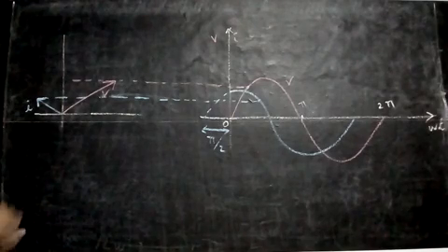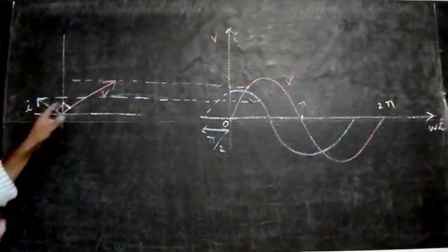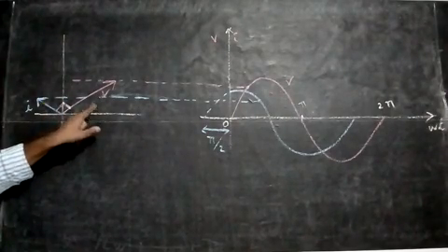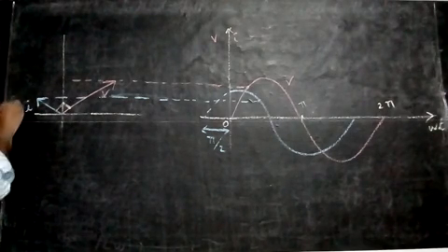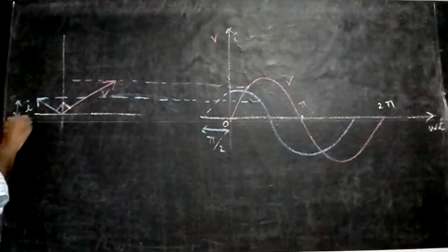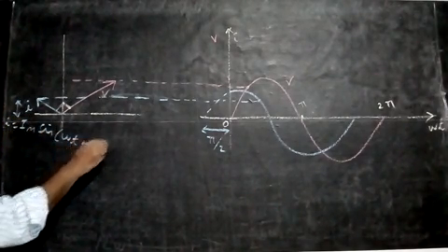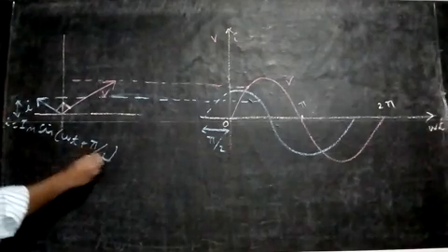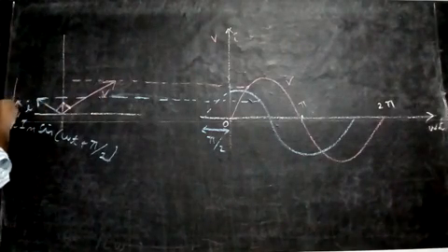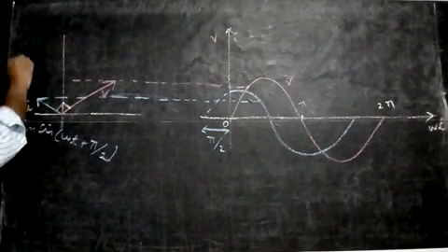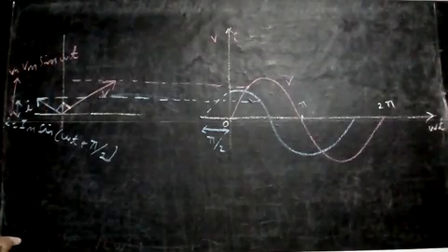So see that now the difference between current and voltage is 90 degrees here. Current is leading the voltage by 90 degrees. Current starts before itself. Again, now you see the amplitudes here. The amplitude for the current will be I is equal to Im sine omega t plus pi by 2. In the book they have written vertically, I have written horizontally here. And for voltage, the amplitude will be V is equal to Vm sine omega t. So this is for the phasor here.